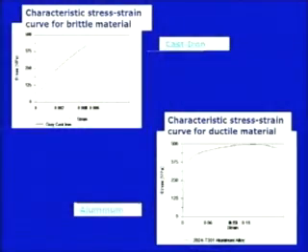If we take another example, aluminum, which is also a kind of ductile material, it is not exactly showing where the proportional limit is, or where the upper or lower yield point is, but we can generally get it, as there is a straight line. That means not much deformation is there, because this is a different carbon composition, but there is the stress component, and beyond that we can easily point out where the proportional limit is, where the yield point is, where the maximum tensile strength is, and what the fracture point is, because we have a ductile material.